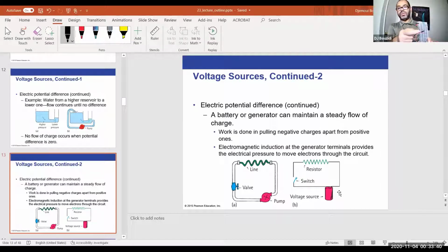And right now I have a resistor of 220 or 210 ohms. Okay, so this is a resistor. Usually it's for safety, because I think this can only support up to 5 volts. This is a 9 volt battery running through. How much current is in here? I don't know. Let me see. Come on. 9 divided by 210. So that's 0.04.